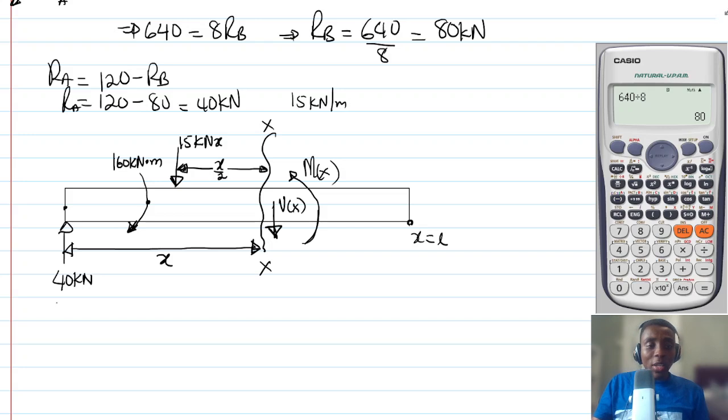So all we are trying to do is come up with a moment about this x. So let's say that this beam is in equilibrium, therefore the summation of moment about section x will be 0. And then we are going to assume that clockwise is positive. Okay, so clockwise is positive, and we are summing moment about the section x to be equal to 0. So first of all, there is Mx, and that Mx is actually the moment because of the cutting. Okay, so we call it the internal moment.